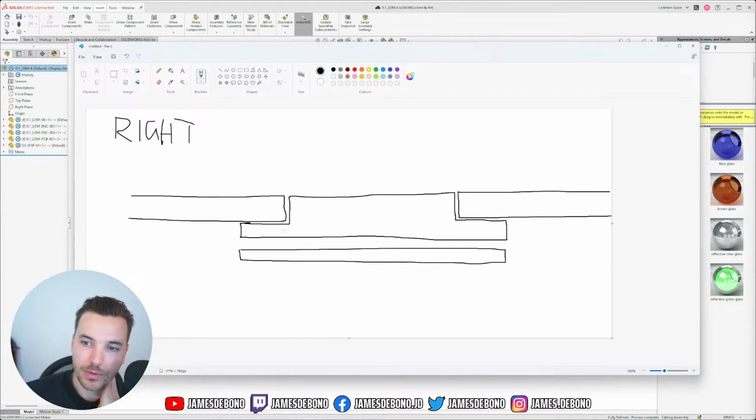But it has two problems. One of them is that because it's attached in this direction, if you were to push it in this direction, it's possible to dislodge it. So if it's glue here that's holding it in, you could break that glue connection. And if it's the display itself that's holding it on, then pushing down on it is actually directly pushing on the display, which is also not great. Most of the time it's probably fine, but it could be possible to damage the display.